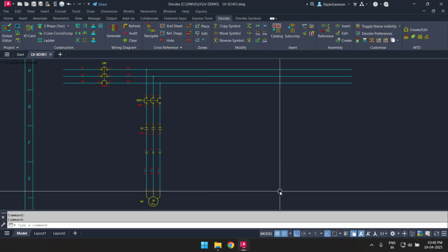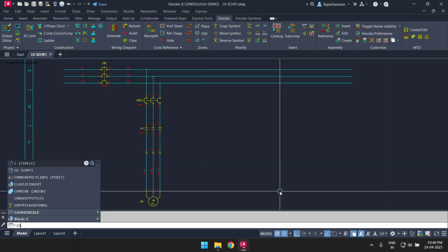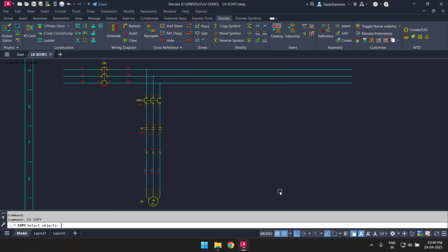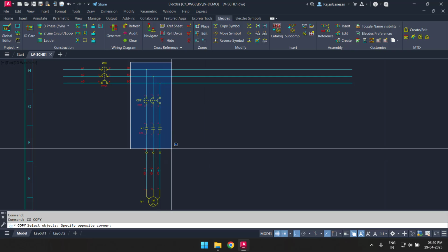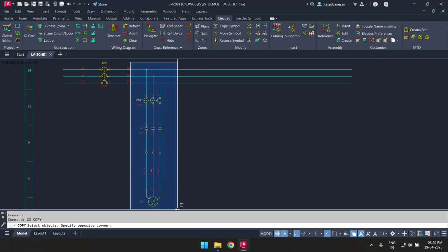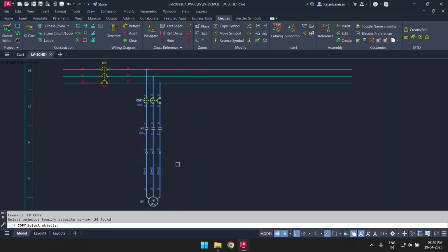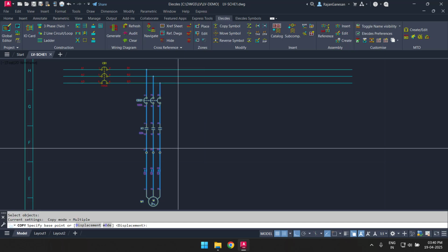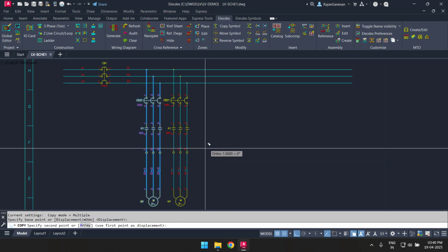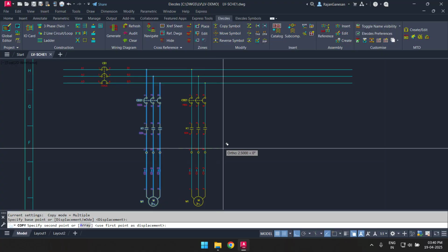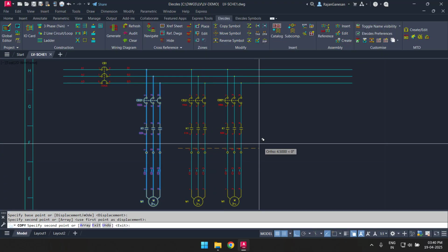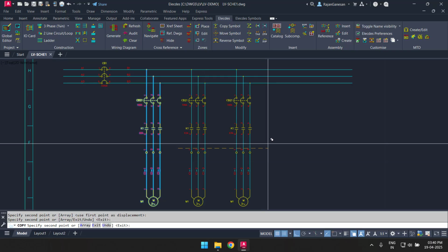Elecdes has added electrical intelligence to the CAD session. The CAD session will now react to the copying and pasting of a component in a smart manner. When I copied the circuit 4 times, the names of all of the components were incremented in a circuit-sensible manner. Without the Elecdes circuit reactors, you would need to click on each component and wire and retype any duplicated tagging.